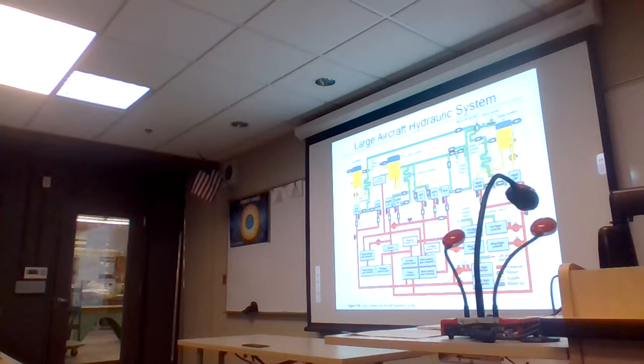Even when no hydraulic system is being used, the discharge of the pumps in some cases is provided with a case drain that goes back into the reservoir to provide kind of a natural cooling loop. So that's what they've done with that. Anything else? I think that's about it.